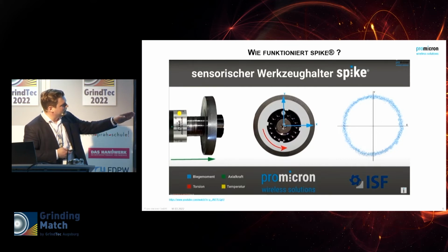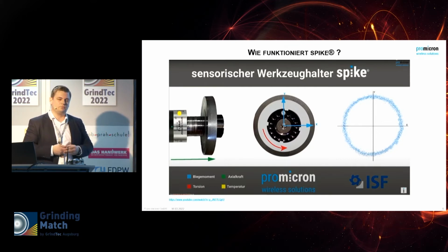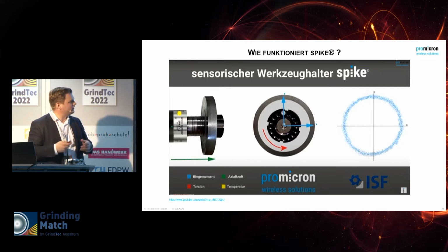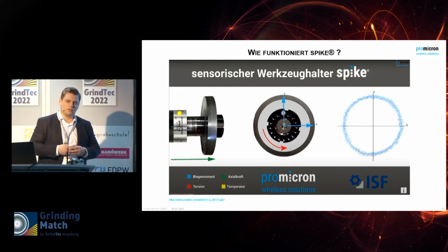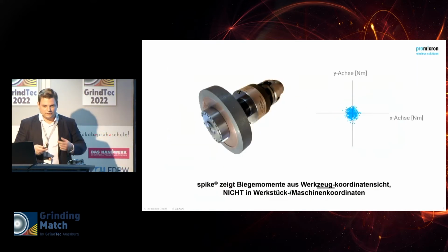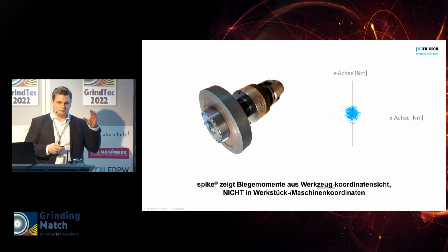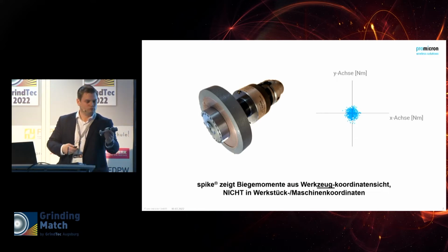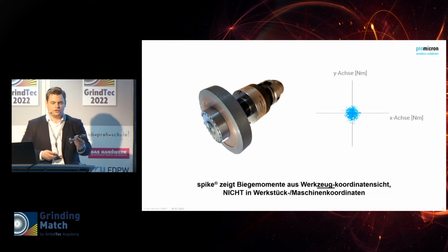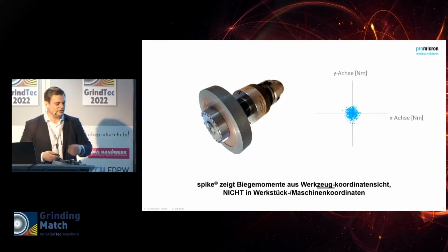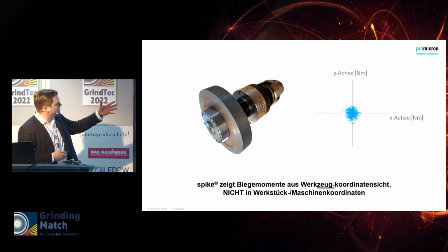And this is how I get this circle, because the system is turning, and on the right hand side the grinding pressure acting on the grinding disc is indicated and displayed. Let me give you a bit more detail. You have the sensors on the holder. That's a typical mandrel, grinding mandrel, 20 diameter. And you have the grinding wheel.